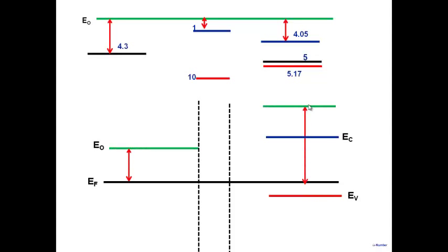We can also draw the vacuum level here, because note, this 5 eV is the separation of the Fermi energy from the vacuum level here. So this is the vacuum level here, vacuum level here. This one we know is 4.3 eV, so we can draw the vacuum level here. And if you look at this particular picture, Fermi energy here is higher as compared to this, so electrons are going to transfer from the metal to the semiconductor.